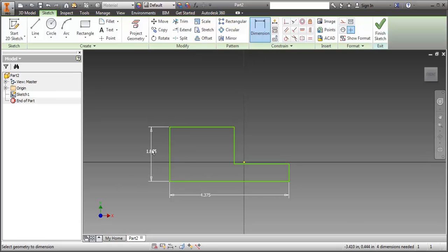I know on the drawing all the dimensions are in fractions, but you have to convert them to decimal. I mean, you can put a fraction in here, but I typically just use decimal. The length here, if you look at it, is 2 and 13/16. So you could put 2 plus 13/16, if that's how you want to do it. Remember, in this little box here, you can put an algebraic statement in there. You can do division, addition, subtraction, multiplication.